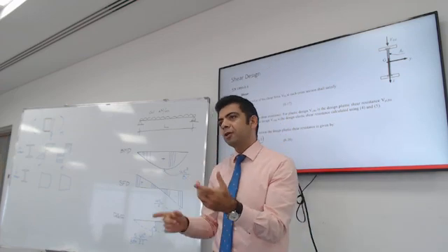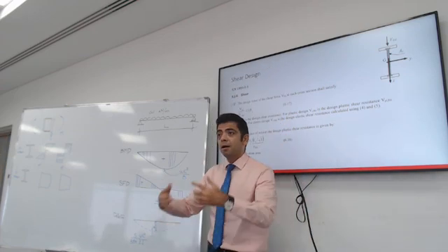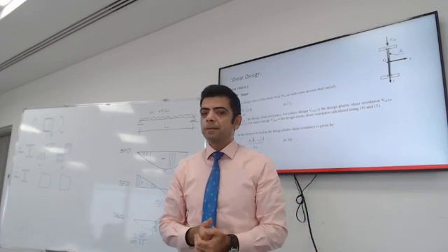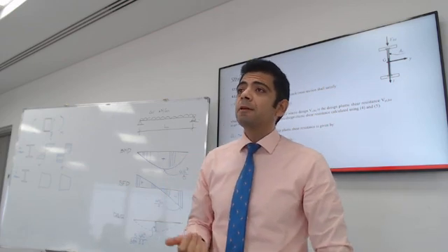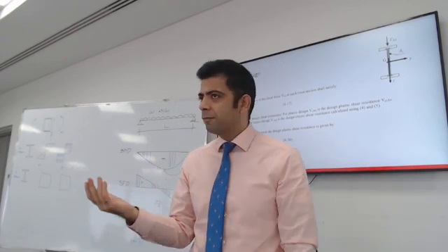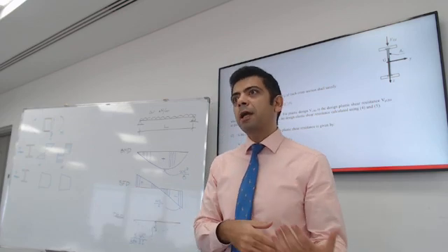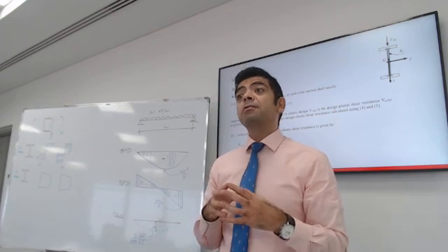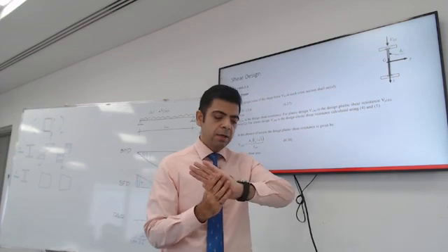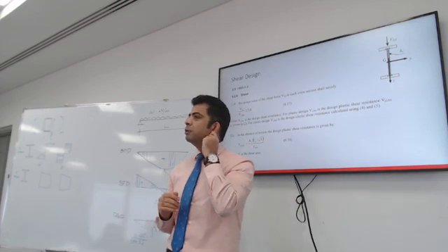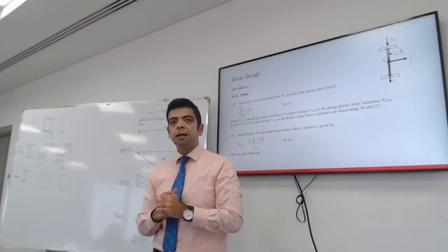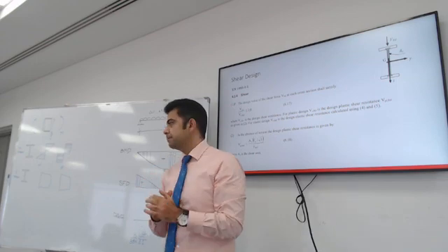And the main factor is going to be the moment of inertia of the section you use. And obviously the material. If you're checking deflection for steel, it's different than if that beam was made out of concrete, because E, the modulus of elasticity, is different. All right, so let's figure out how we design the shear capacity of the section.